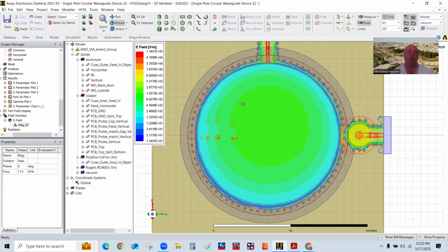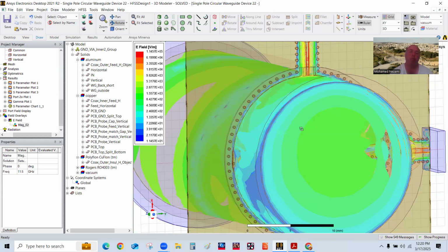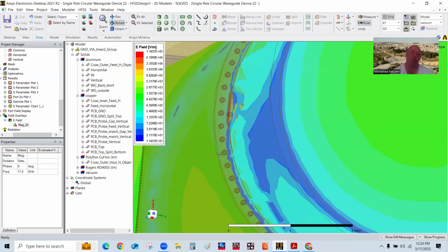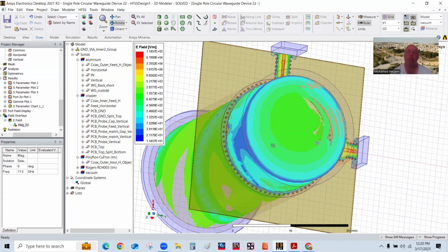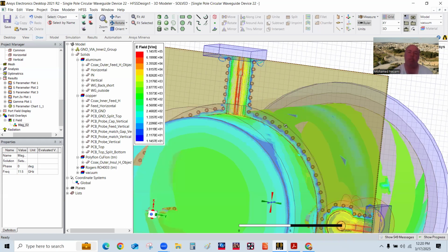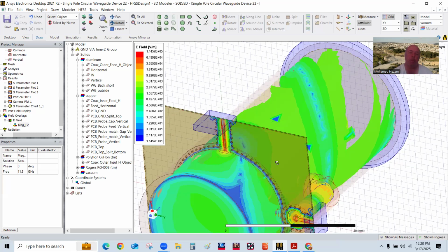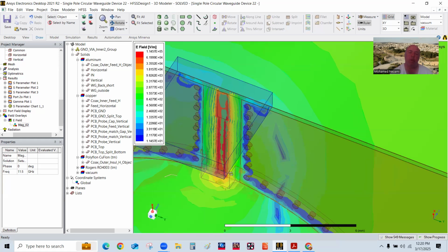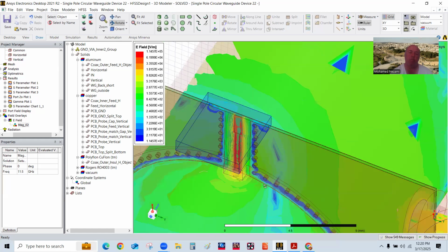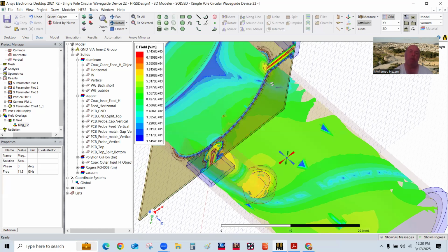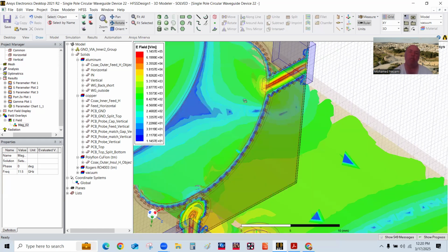Same thing for the board at the aperture of the waveguide. You really have to place these vias carefully. If you're not careful, the signal is going to leak into the board. And the same thing in here for the rat mouse hole. This one I had to work very hard to optimize, the mouse hole in here, so that the signal exits without any interaction with the microstrip line. Okay, and you can see that right here.